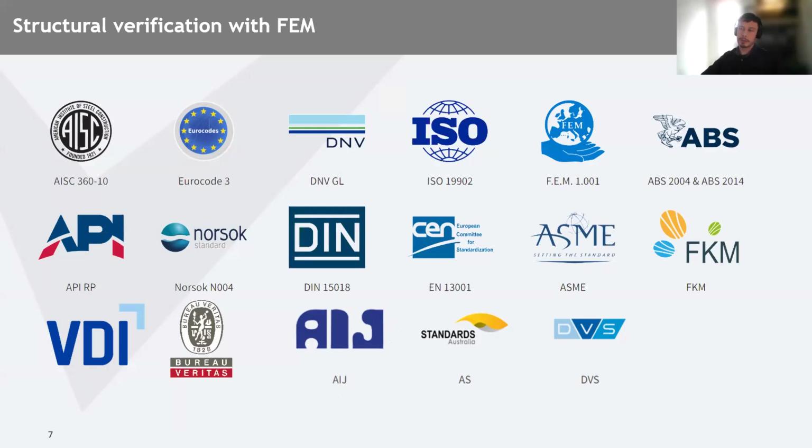Your structure model can be automatically checked to see if it meets the criteria for a certain standard, and also you can optimize the structure for the exact standard. So you don't have to just calculate the stresses and do the optimization for the stress or deflection. You can optimize your structure so it meets the exact standards from the various industries.